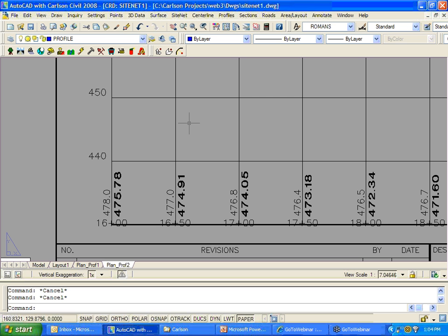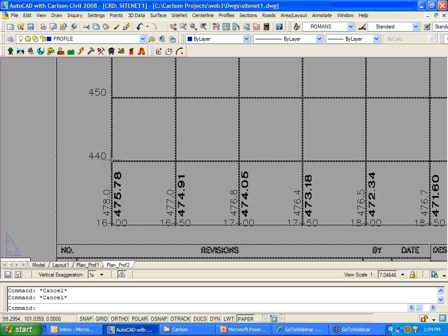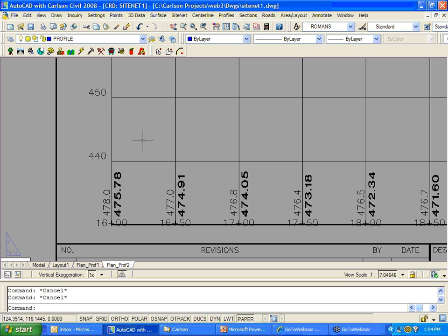So basically, what you would do is open up that title block drawing and see where 0,0 is. Then another option, again, that I've honestly not tried, but now I'm going to go try, is to maybe leave 0,0 and move the base point, BASE, and see if that triggers this correctly. That might be another solution. So that's an interesting question. I'm going to experiment with that myself.